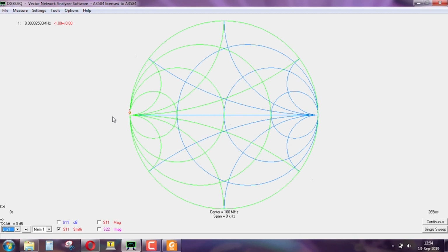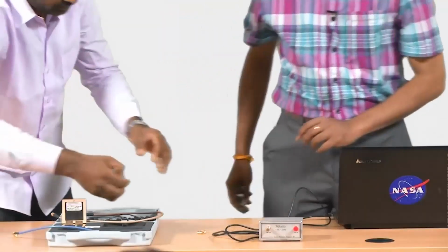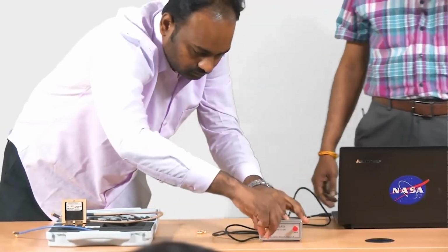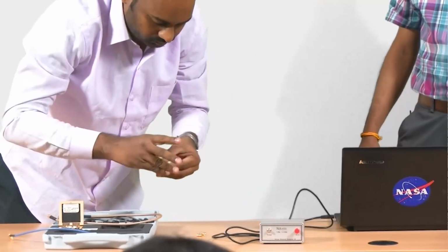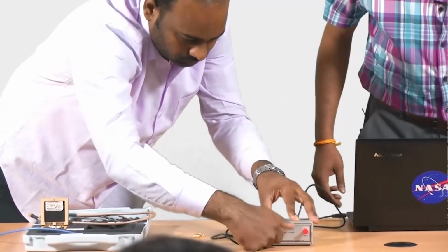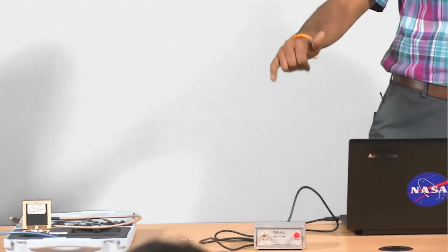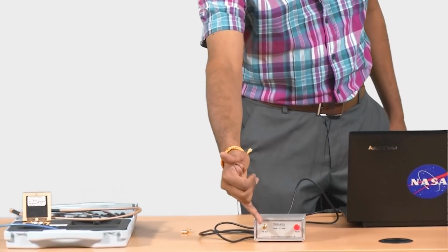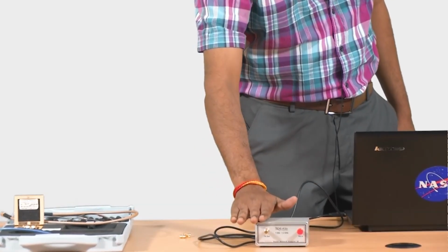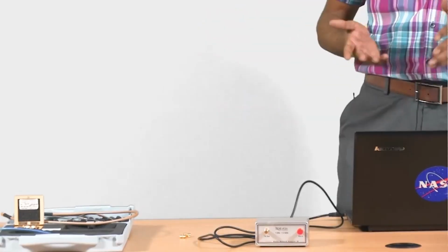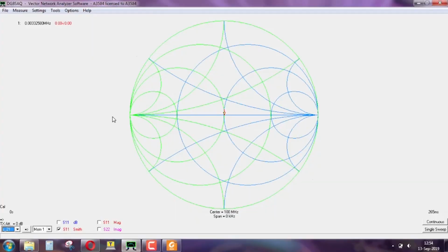Now I think you can connect a 50 ohm load. Remember that once again the connectors have changed, all right, and this is a 50 ohm load, and this TX RX output is rated for 50 ohms. Okay. So it should come at the middle, it's right at the middle, so it is impedance matched. Okay. So these are some small things we can do.